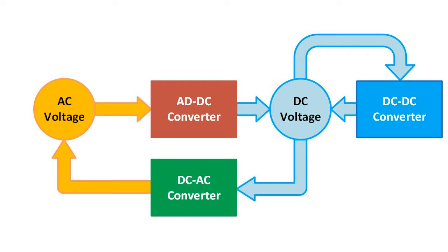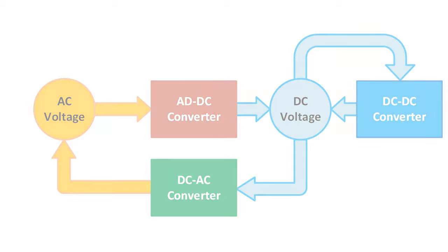Another type are DC-DC converters, direct current to direct current. These are used for increasing or decreasing one-way current. Electronic circuits and built-in elements for their functioning need different voltage potentials. With the use of DC-DC converters, we integrate voltage potentials in electronic circuits. The most common voltage potentials are 12V, 3.3V, 5V.